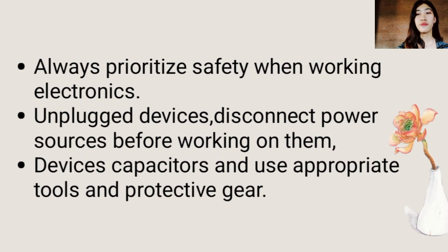and always prioritize safety when working with electronics. Unplug devices, disconnect the power sources before working on them. Discharge capacitors, and use appropriate tools and protective gear like gloves. Avoid high voltage circuits without proper training and safety measures.